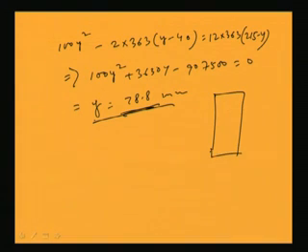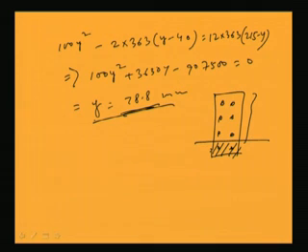Okay. So, if h by 7 we know, now what will we do? If rivets are there, I am not just making the exact number. If the neutral axis is here, then this is the compression zone and this is the tensile zone. So, when I go to find out the stress, I have to know M by I into y.